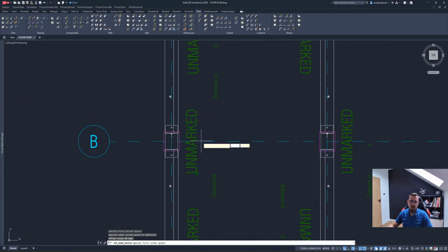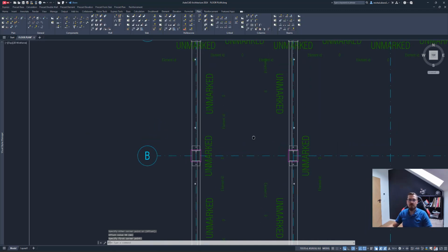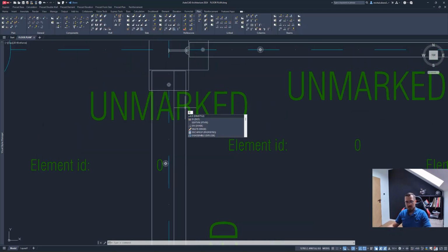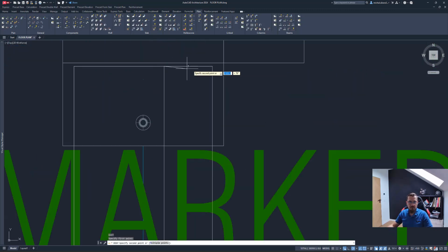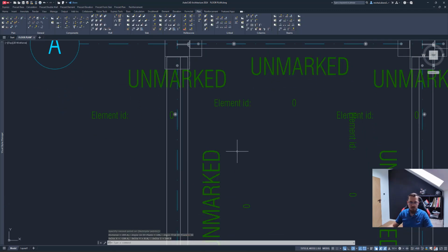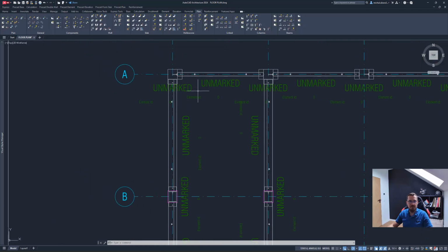Like this. And now my recess is prepared, so I can now draw the elements. The depth of the support, as far as I remember, again, that's 150 mil for the ledge. So let's say we'll support that by 120 mil on both sides.